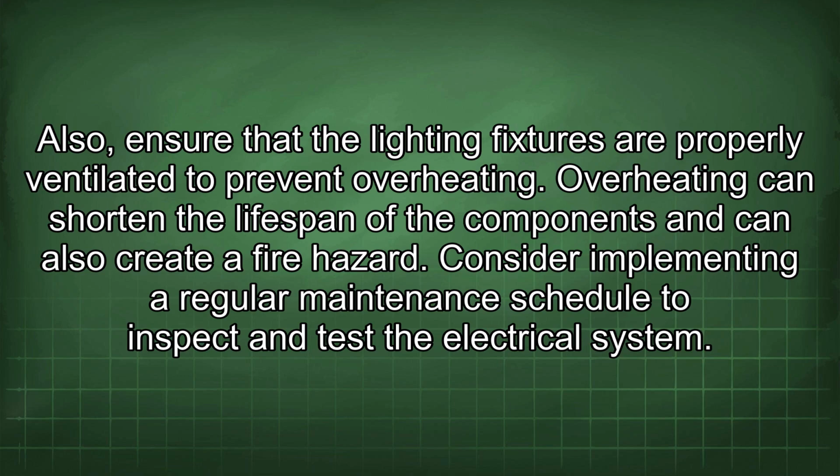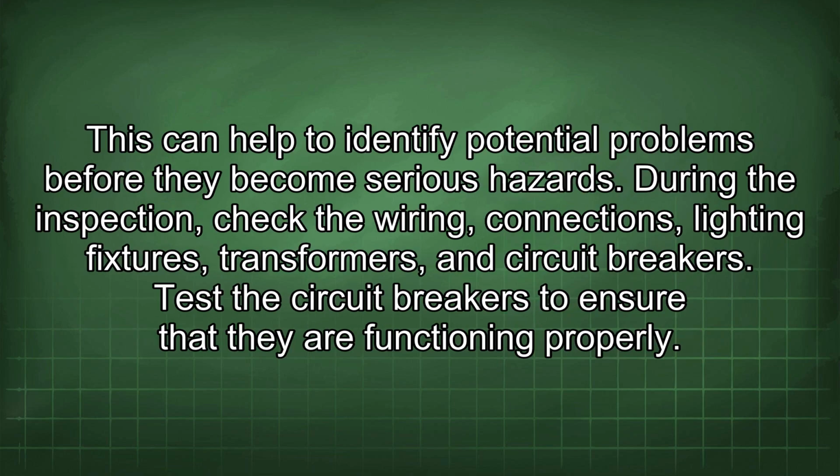Consider implementing a regular maintenance schedule to inspect and test the electrical system. This can help to identify potential problems before they become serious hazards. During the inspection, check the wiring, connections, lighting fixtures, transformers, and circuit breakers. Test the circuit breakers to ensure that they are functioning properly.